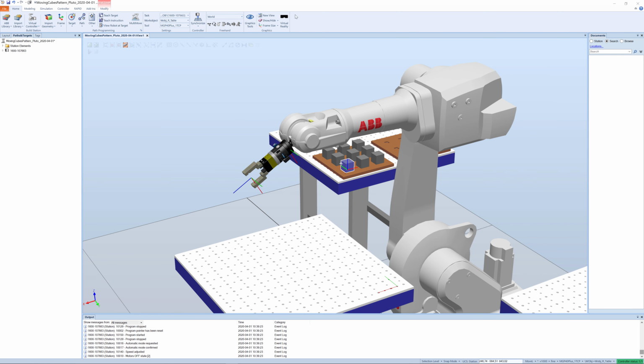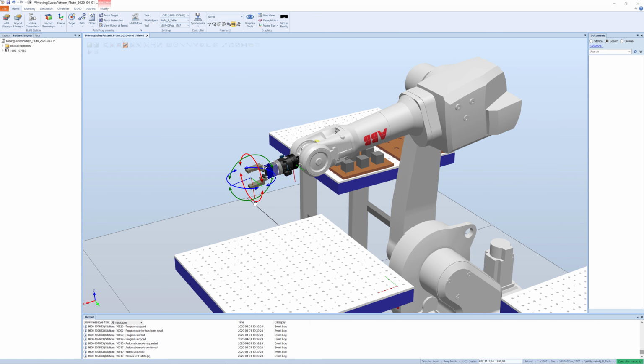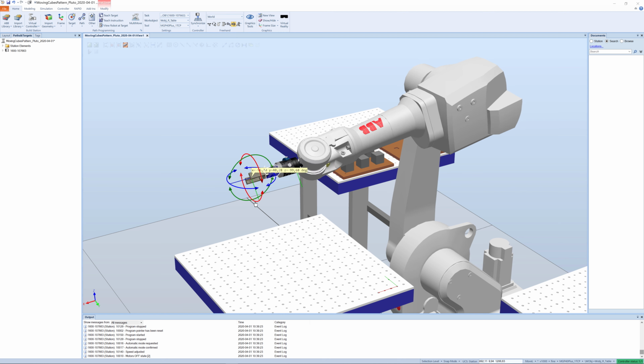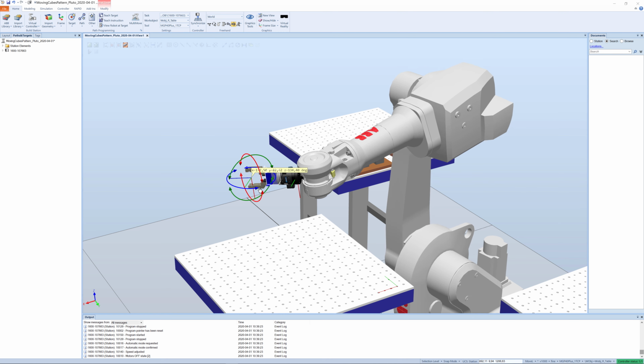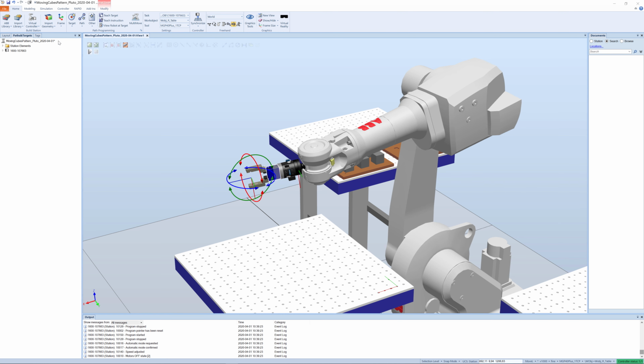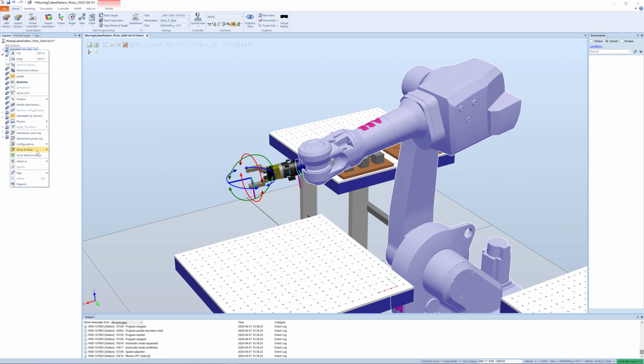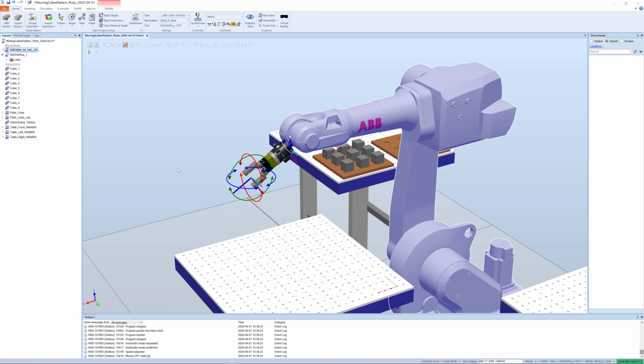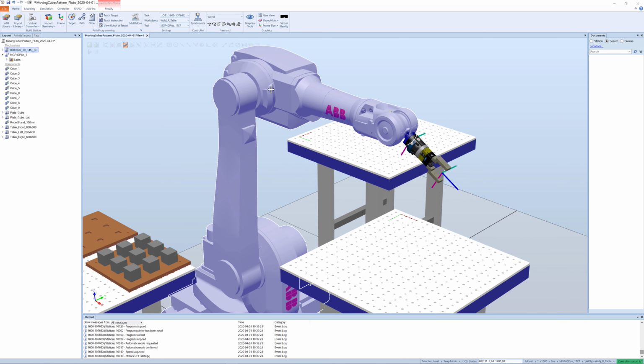By the way, we can see how that operates if we do this job orient, click on the tool, and then we can do this kind of manipulation. You see that we have a tool center point, that's fine, and looks nice. Right click on that one, move to pose, jump home, and click on that again so we get out of the tool center point.